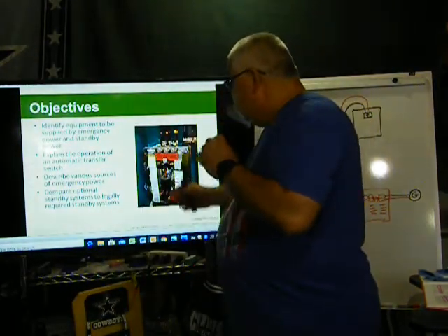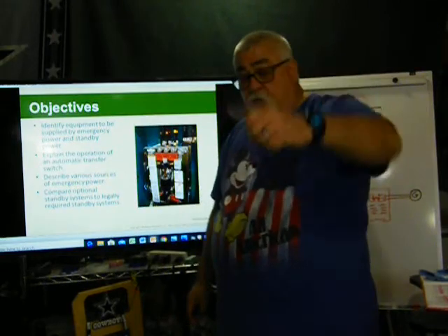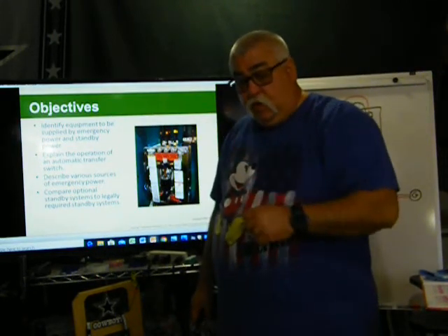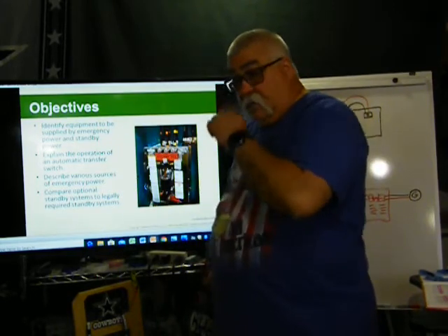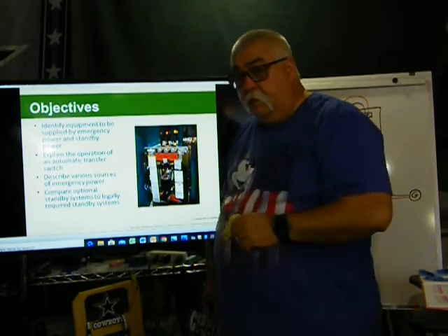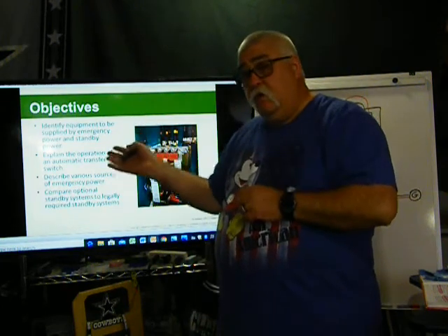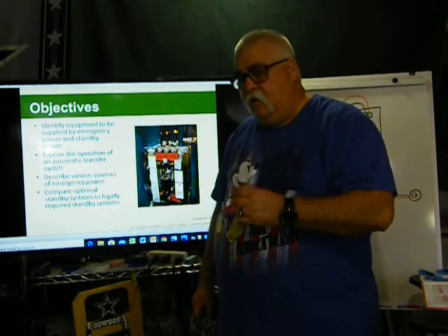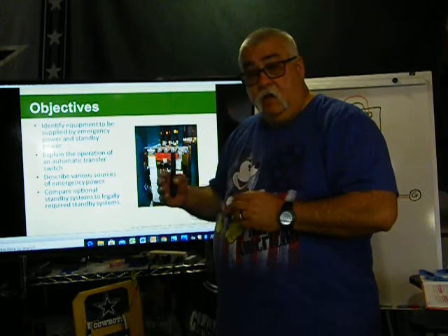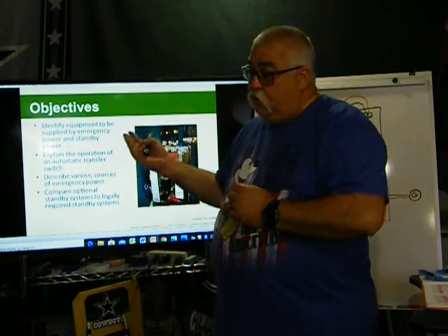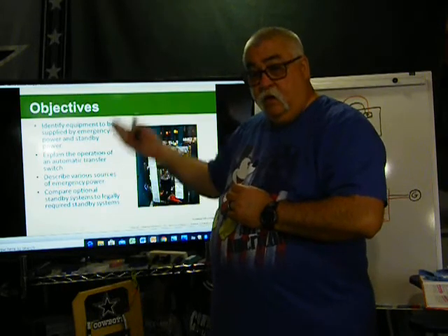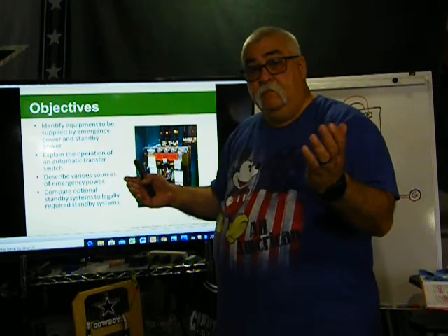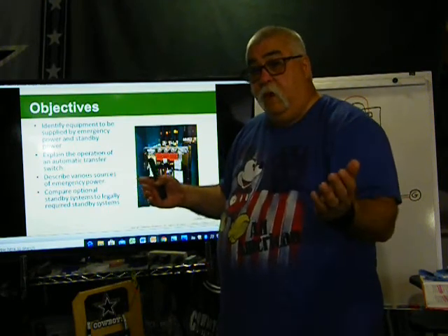So we'd go over to the transfer switch. It has a board on the bottom, and we put it on test. Once we put it in the test position, because it has like a computer inside, it would turn the generator on. It had like a 30-second or a minute delay, whatever it was. The generator comes up, runs up to full speed, and then we transfer over. So it would transfer all power to emergency power.